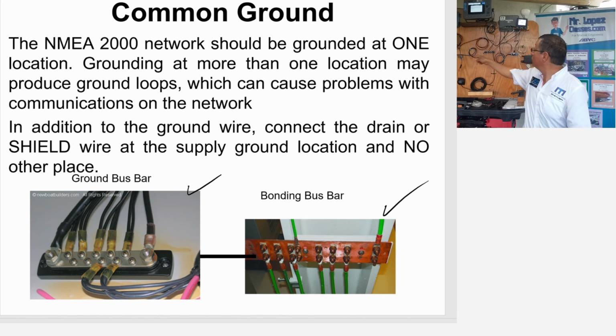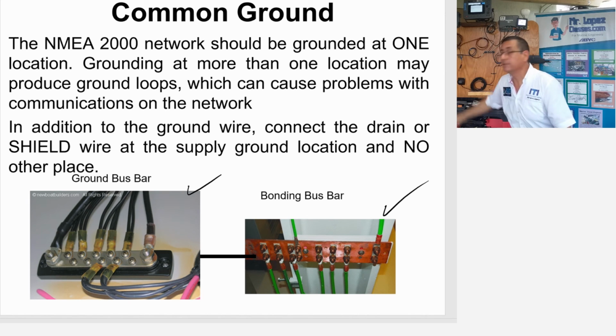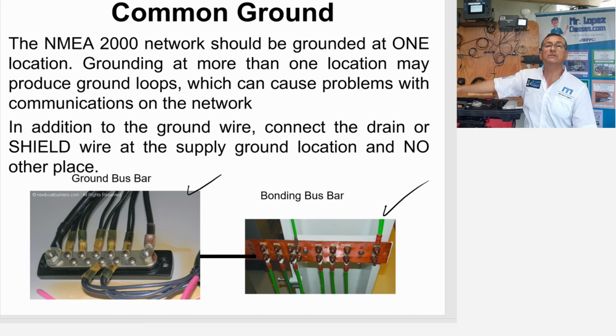Where is the ground bus bar of the backbone? Ah, it's here. It's separated 2 feet from the air conditioning equipment. Excessive electromagnetic interference. Normally, when people install additional air conditioning equipment, they immediately introduce too much electromagnetic interference around the backbone, especially around the ground bus bar. The ground bus bar should be protected and isolated.